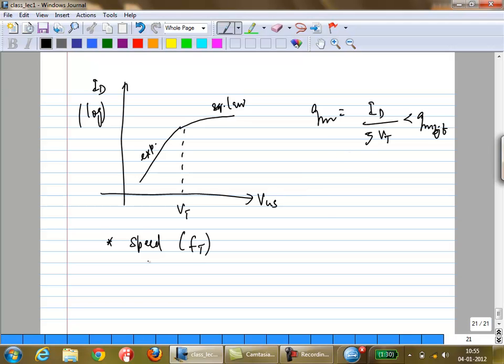And obviously you're interested in current density, because that is what will cause you to go into subthreshold. If you have a very large device and you put in very little current, your VGS minus VT will be very small. That is when you have a very large chance of going into subthreshold. So you have to be careful.